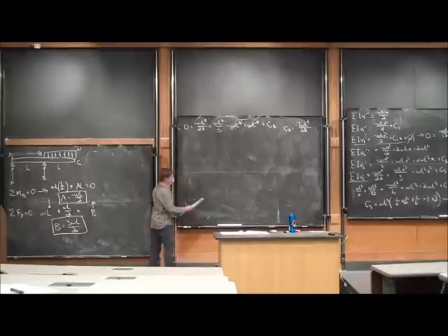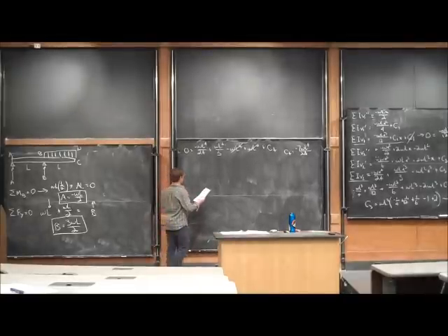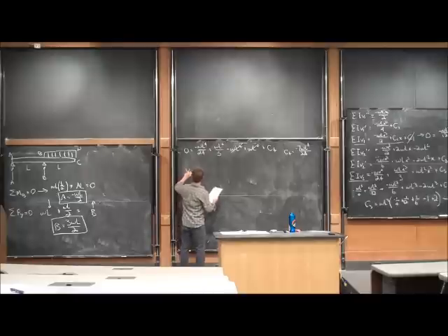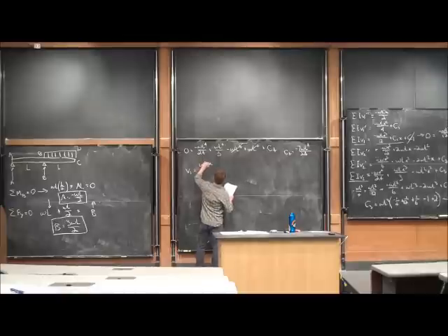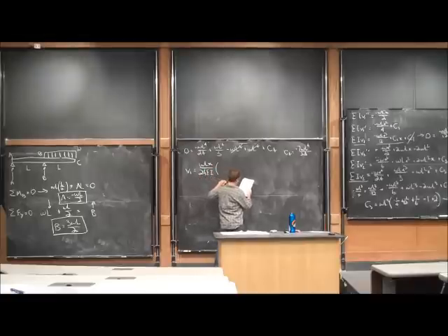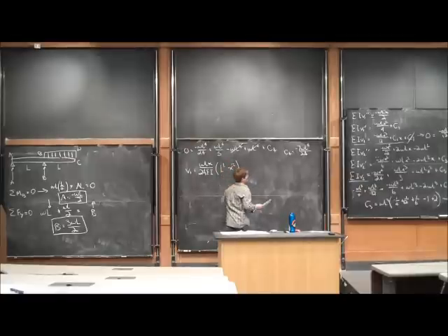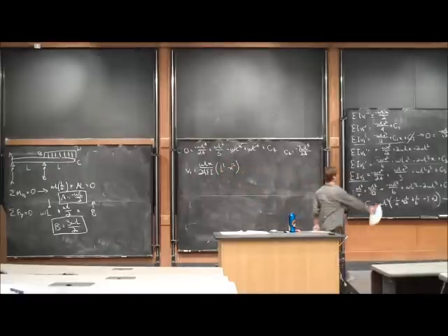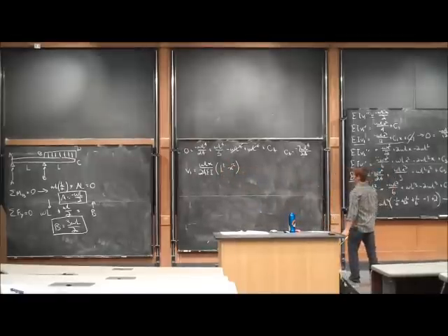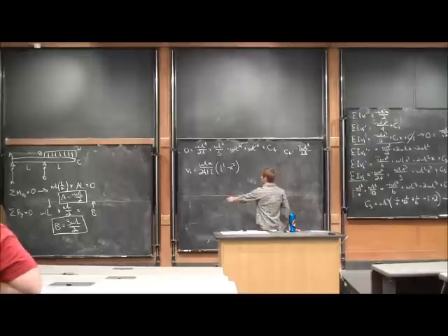So in this case, now that we're done solving all these equations, we can see that V1 is going to be equal to WLX over 24 EI times L squared minus X squared. This is after applying that C2 was 0 and that C1 was WL cubed over 12 and did some factoring. This is valid for 0 is less than or equal to X is less than or equal to L.